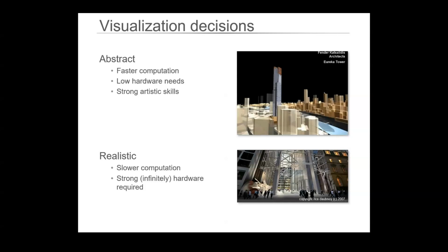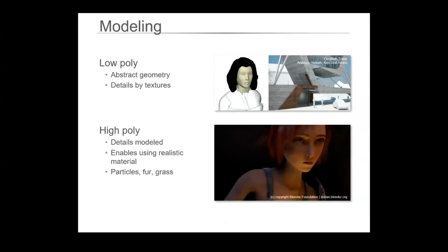They take more time, obviously, and especially out of ArchiCAD, a really high quality rendering can take overnight or longer sometimes, depending on what it is. So if you want really good renderings, I don't recommend doing them in ArchiCAD. I bump them out into something else, and I've been playing around with Twinmotion myself, and that seems really, really quick. It's probably one of the quickest that I've experimented with in my life.